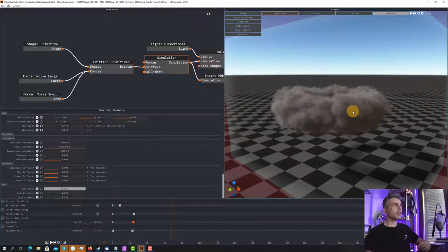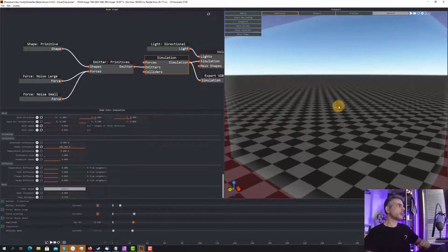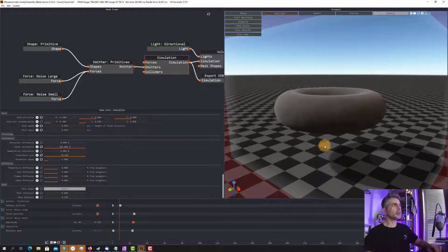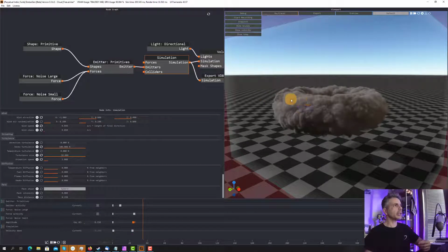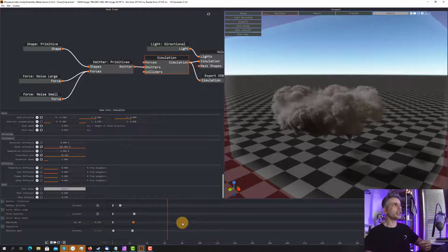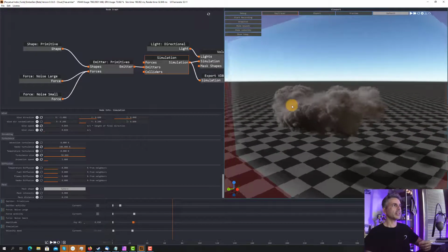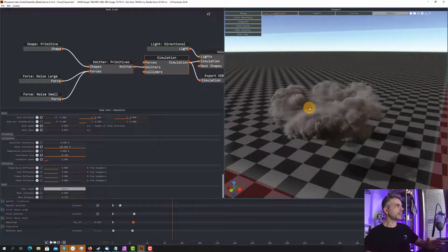It is a nice effect, but I like to apply everything all over with a bigger scale. So we'll have some areas with this kind of turbulence density, and other areas with higher density and a really nice variation. So turbulence sides, let's change from 1. Animation speed can stay maybe slower to 1, and turbulence sides will be really big, so 50 times bigger. You will see just some areas with a turbulent density falling. So you see there, for example, here we have a higher density, and we have other bigger area that are losing the density, and that's really nice because with a simple emitter we are creating some complex cloud.